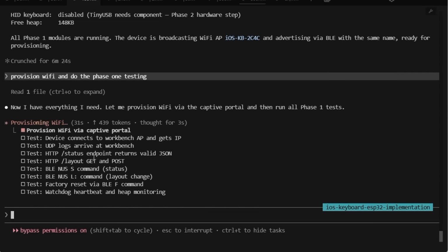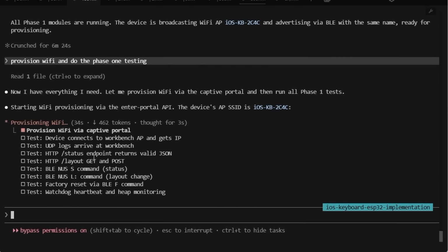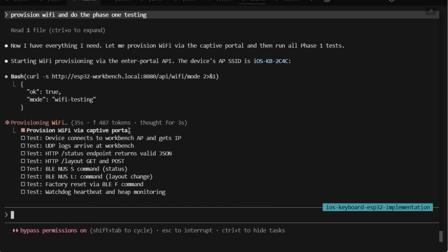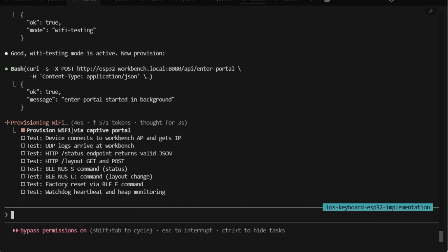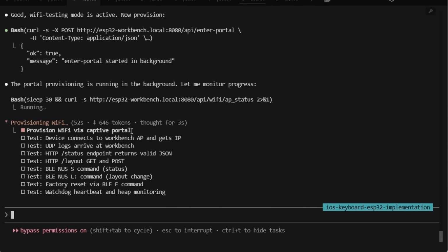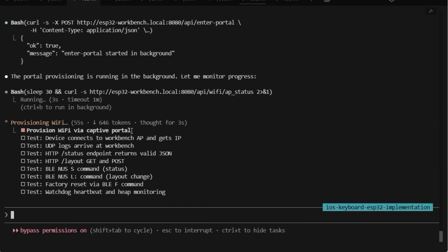And now it starts again with some to-do list. The Raspberry Pi connects to the ESP32's captive portal, enters its Wi-Fi credentials, and then the Raspberry switches and offers an access point, and the ESP32, because it now knows the credentials, can log into the Raspberry Pi to do the further tests without bothering my home network. Everything is done in the test environment.